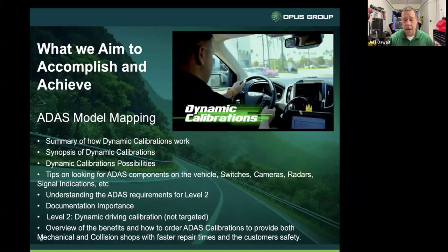And we're also going to talk about, on the tool, ordering calibrations, right? If a lot of you have Drive Safe or Drive Pro, I'm going to show you where to go in the tools in order to get those calibrations ordered, or you can follow the instructions on your own personal aftermarket tool if you're using one to do these calibrations. But the main thing is understanding the calibrations and also understanding when they need to be done. That's the biggest thing.